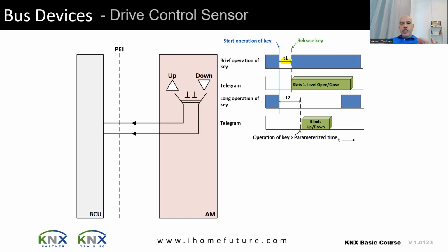Normally, what you put here is a slightly higher number than this. So if it is taking 10 seconds, so I know that the motor from down to up, the entire journey will be 10 seconds. In my parameters in KNX, on the driver itself of the relay, I put, let's say, 11 or 12 seconds, meaning that if I kept pressing here and then I move my finger, then after 12 seconds, automatically it will stop. It will not send power anymore. Okay? And this is why the timings are here. So depending on the time you are putting, then you are controlling the motor up and down.